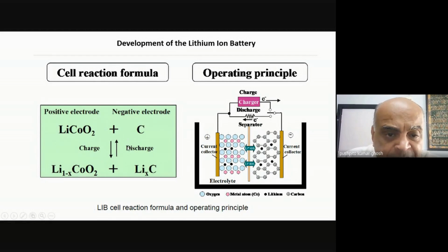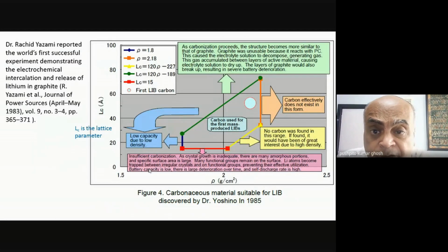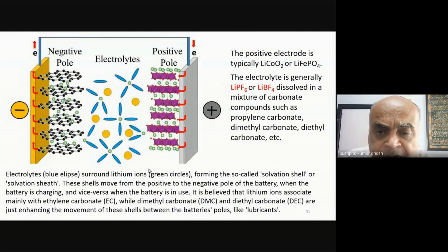And when I'm charging it up, I'm doing exactly the opposite. I'm pushing electrons into my carbon and I'm taking out electrons from my cobalt, and it is basically going into this. That's effectively what is happening. Obviously, we have not talked about the ionic conductivity. Lithium cannot just hop around from anode to cathode without any electrolytic conductivity. It needs electrolytic conductivity. Maybe before the other electrode, I'll come to the electrolytic conductivity.